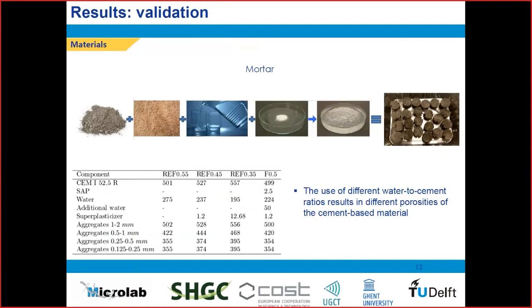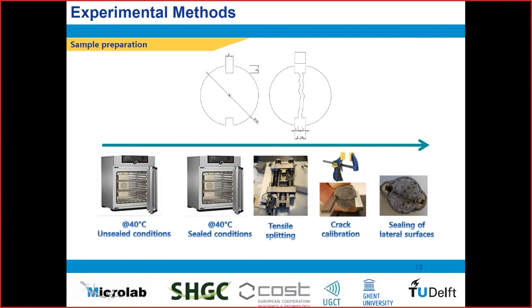So for this experiment, we prepared mortars with different water to cement ratios. These were the samples. They were cylindrical with some grooves on them. These grooves were designed on purpose because we wanted to scan both uncracked and cracked samples. And these grooves allow us to create a nominal crack width that was quite within a certain target standard deviation, which is actually, if you know what I'm talking about, quite difficult to obtain in our field. So this was kind of necessary.